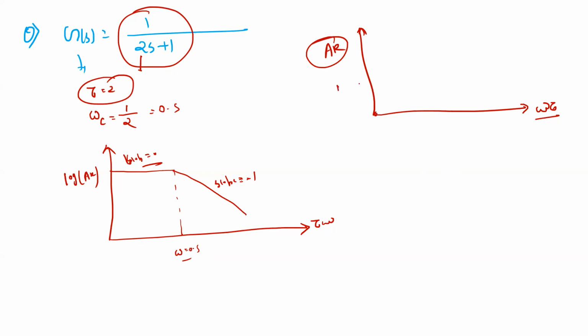But yes, this one is also a Bode diagram. Again, the shape will also look like that. Here, omega is equal to 1 upon tau, and that is equal to omega c, which is called the corner frequency. Is it clear?